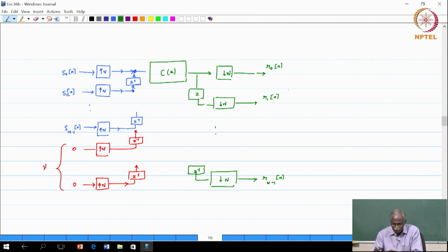So, basically from this set of outputs, I have to get S hat of n, and that is through the pseudo inverse, and that pseudo inverse actually requires you to have this entire vector. So, do not throw any of these samples away, not yet. The removal or the exploiting of the redundancy and removing it is actually implicit in the pseudo inverse computations that we will show.